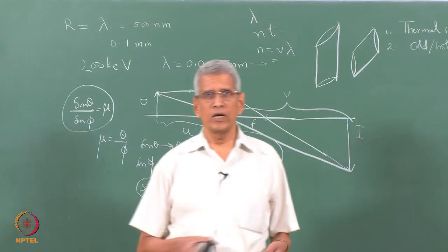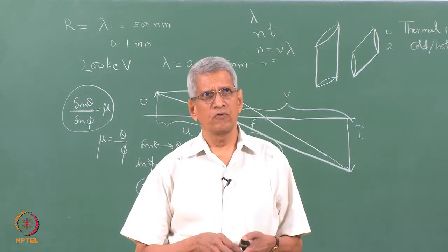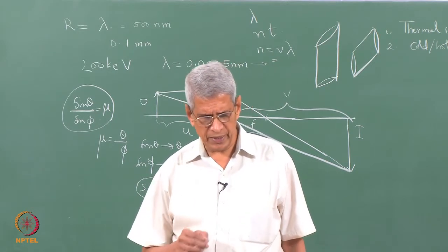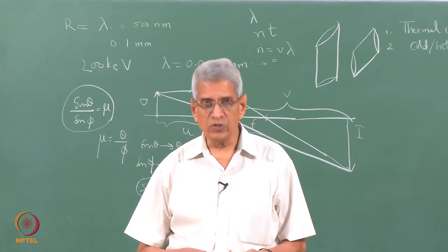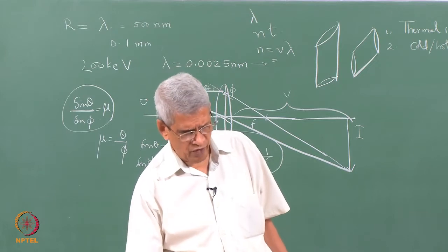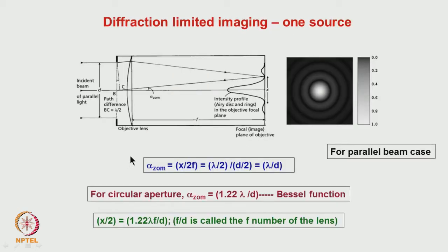So, essentially in any microscope, the aberration comes one from the lens which we are using, and the other aberration, like the chromatic aberration, comes from the source of the radiation itself, whether the radiation is highly monochromatic or not. Both these together decide all the aberrations which are going to be there. All these aberrations can affect the resolution of the instrument. This is what we will discuss shortly, how these various aberrations affect the resolution.